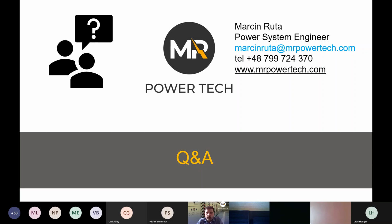Because you have a bunch of new solutions which you can use to prevent shock hazard and things like this. But in case of fault, if your switchgear is not internal arc classified or arc resistant, or for low voltage, you cannot make an assumption that it's safer. It can be a perfect old switchgear, 40 years old, with the best maintenance possible, and it will be okay. And it can be brand new, which will generally be the same situation if you do a one-to-one change. And there will be no difference for the arc flash calculation, maybe small.